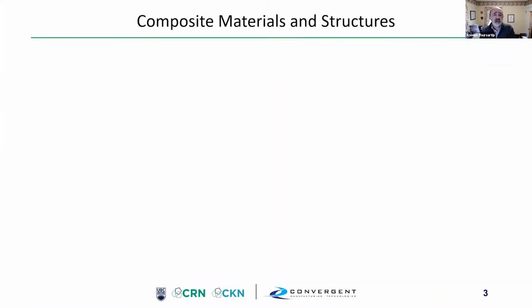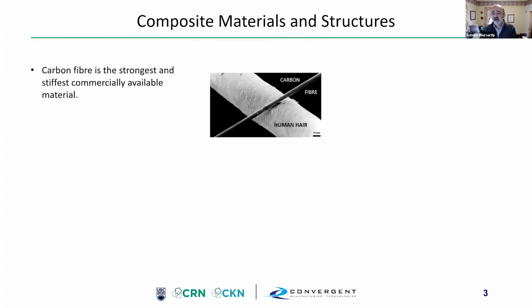In my case, I work in an area where manufacturing is really, truly difficult. And that is, we work in the area of fiber reinforced advanced structures using carbon fiber. It's the strongest, stiffest material available. A single carbon fiber is about 5 microns in diameter. We literally take billions of these fibers, put them together in a gooey mess, the matrix, and we basically get double-sided sticky tape. And what we do is we use this to additively make very large, complicated structures in essentially one step.